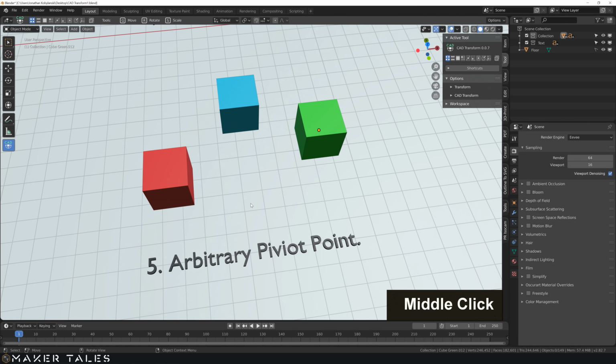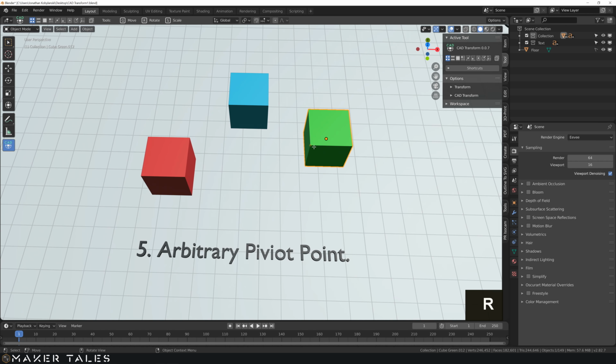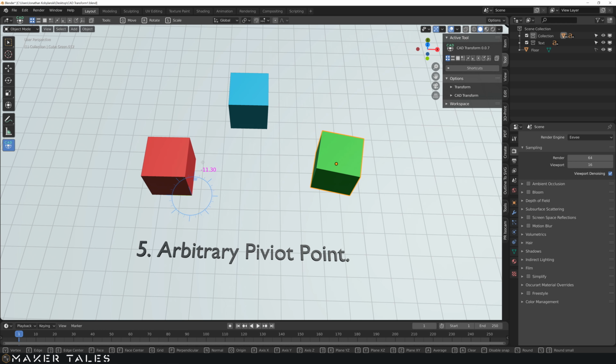And very similar to the move operation, we can do arbitrary pivot points. So selecting the object we want to rotate, let's hit R, let's hit the anchor point location, which will be the bottom of this cube here, and on top up here. So we now have an X axis, and you can see we're using this as our pivot point. Of course, here you can snap and all the rest.